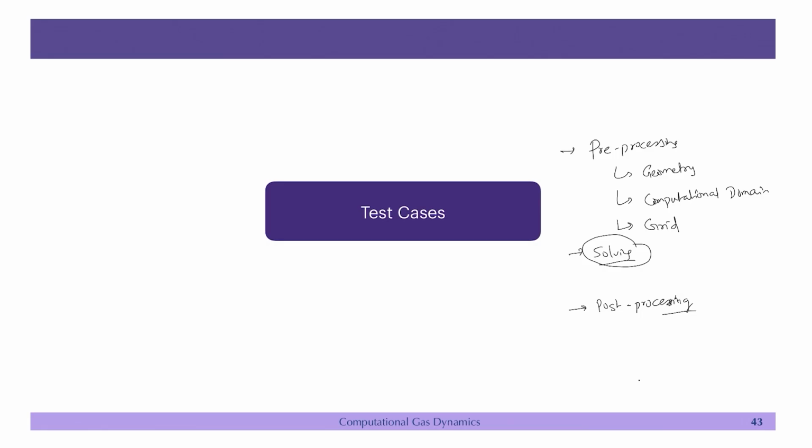Similarly, in terms of open source solvers, OpenFOAM is one, but you have, for example, SU2, which is good for, let us say, the compressible flow problems. You have XCompact3D, and there are actually many more solvers. If you just go and search for open source CFD solvers, you will find many of these, because the name itself is open source. So basically you have the source code available, but the responsibility lies on you to set up the solver. They may not have extensive validation cases. They may not have a very good user manual because they are open source by the name.